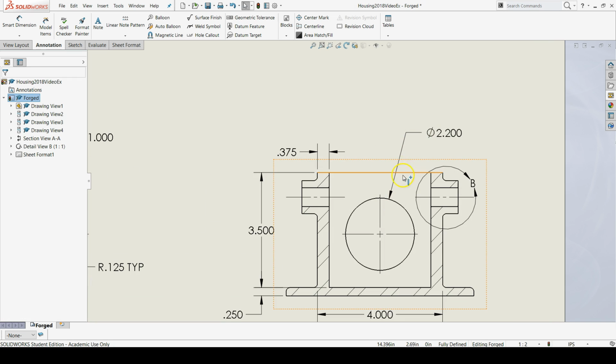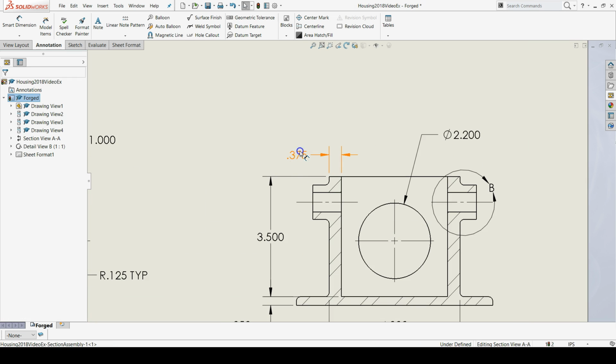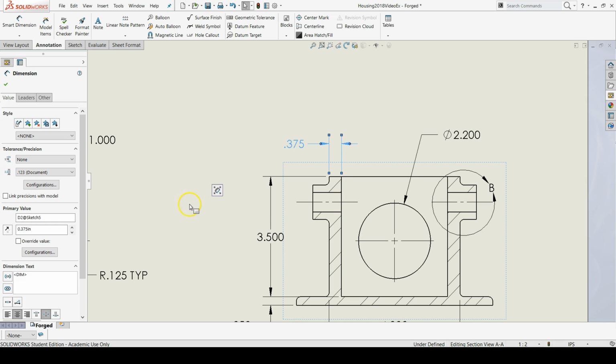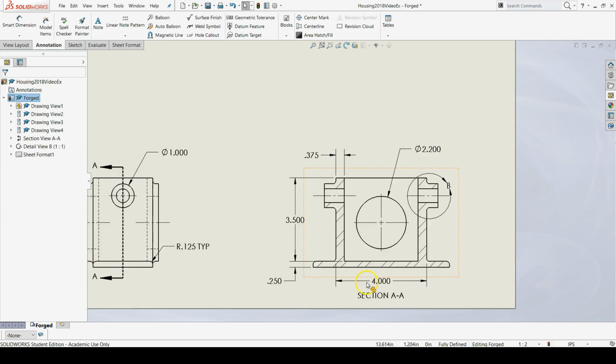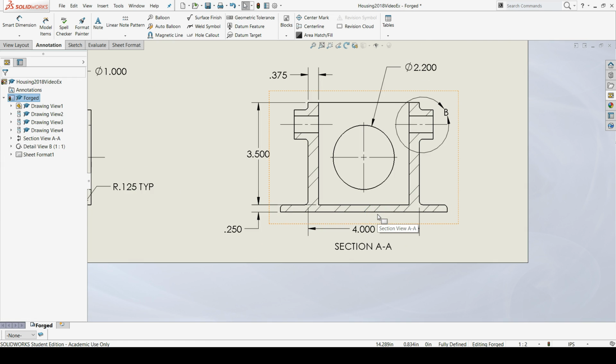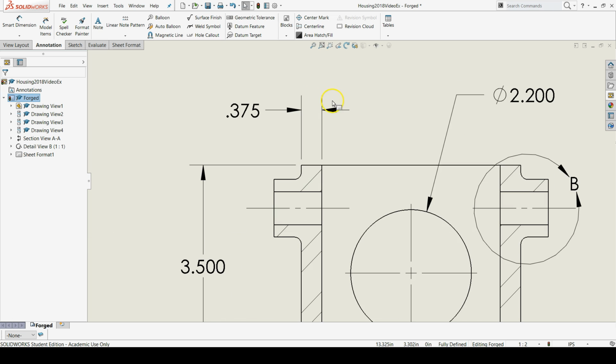And all of our dimensions need to be a certain distance away from the actual drawing view. We don't have to be an exact distance, just as long as we're above the minimum, which is 3.75. And how I can gauge that is I can hover over the extents of the drawing view, and I can look down here at the coordinates while I hover over that point.